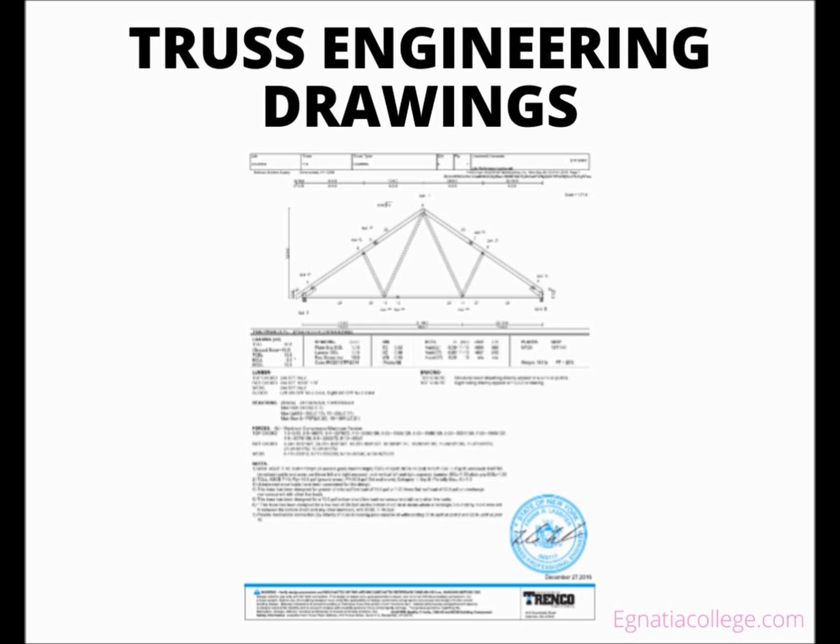Carpenters do not usually build trusses, but the same packet of engineering drawings that go to the site with the trusses is also used in the truss shop to build the trusses. It is very important for the carpenter to read all the information on the detail, even though it might not all be needed to set the trusses on the building.